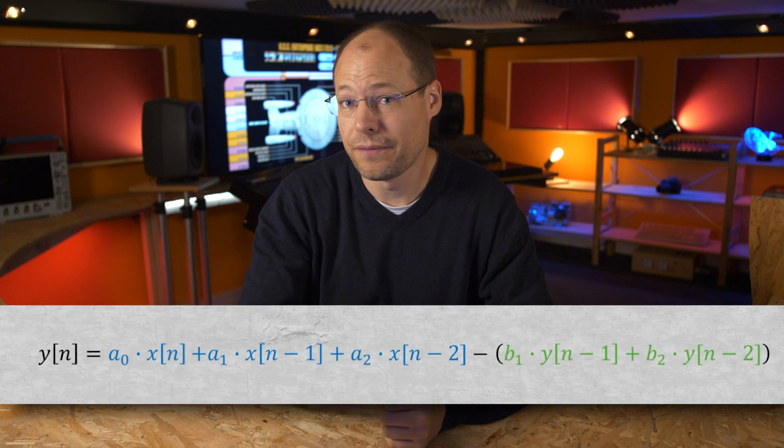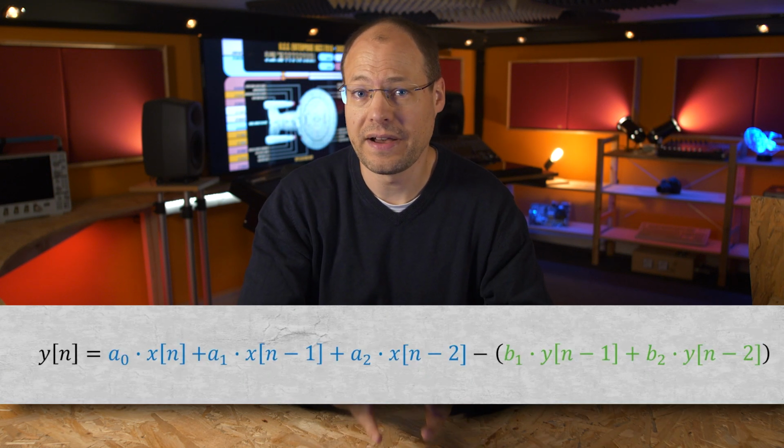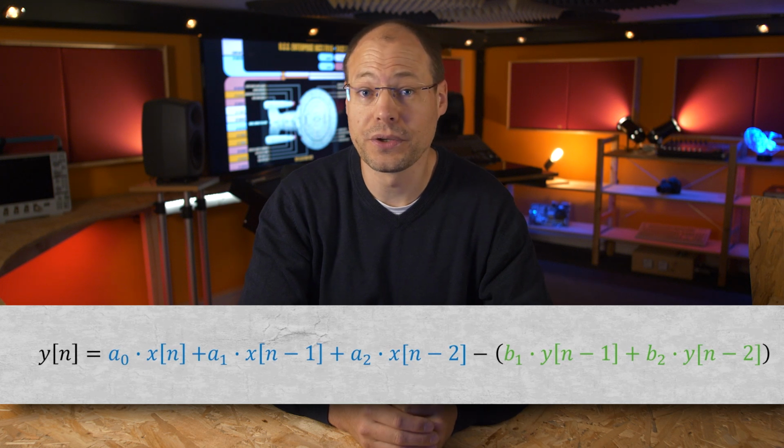So there are 3 additions, 1 subtraction and 5 multiplications for the individual coefficients. For this, our Cyclone FPGA offers dedicated 9-bit multipliers. Since we want to process our audio data with 24-bit, we need at least 3 DSP multipliers for each multiplication. In fact, we even need more multipliers as the coefficients unfortunately require quite high resolutions.